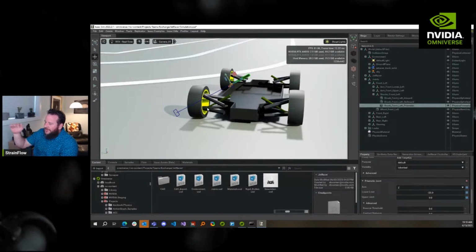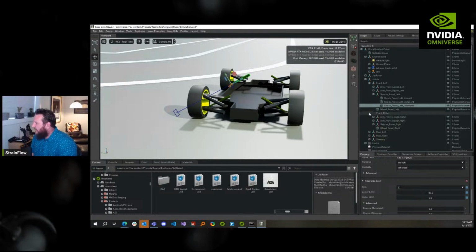When we set this car down with 1 kilogram, I think I want those shocks to go about a millimeter. With my real car, when I set it down, first of all, there's no preload at all, so the joint starts there. And then when I set it down, oh, you know what? It's going more than I thought, maybe more like 2 millimeters. So maybe it wouldn't hurt to soften those springs a little bit. Should we see if that helps?